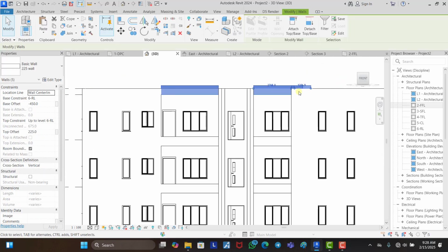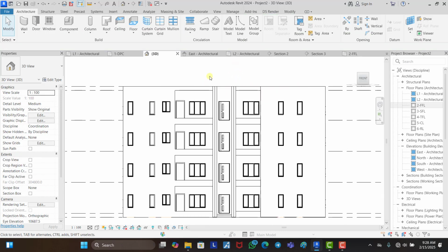Aha, now we've selected all of them. They are 5 in number. Good, you can see them here. Number of selected items 5. Then we check 0. We don't want any upstand. Perfect. Then the drop down, which is 450, is very, very good. Perfect. So this is what we want.